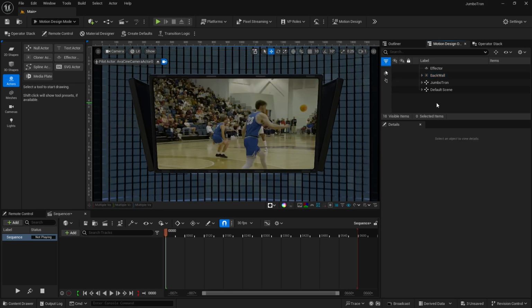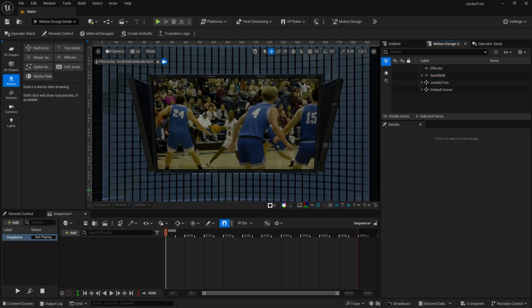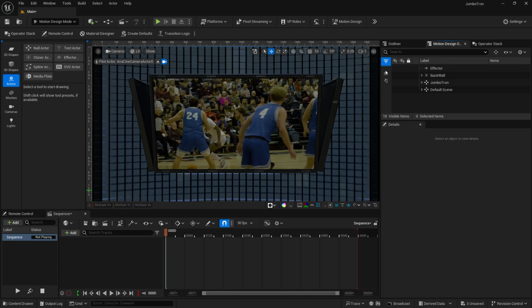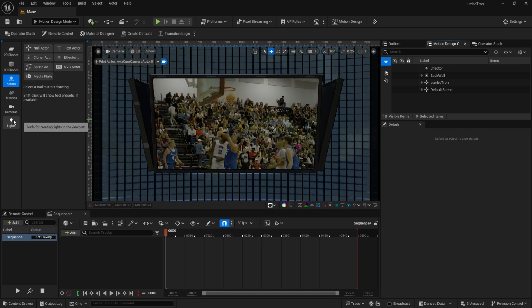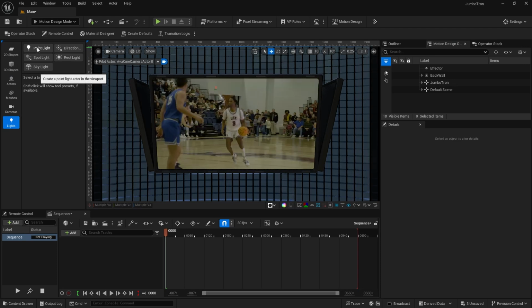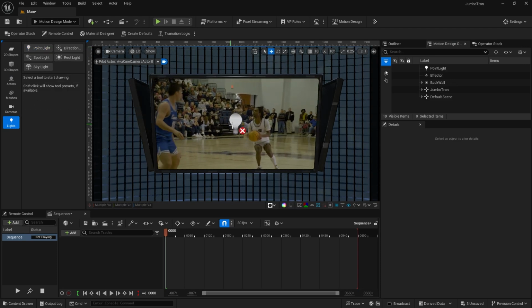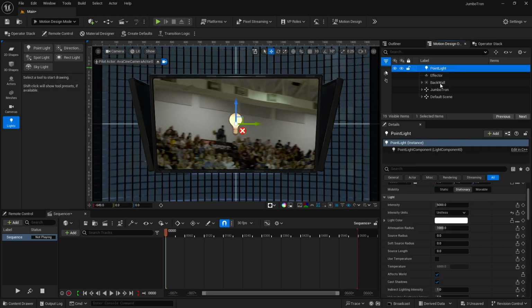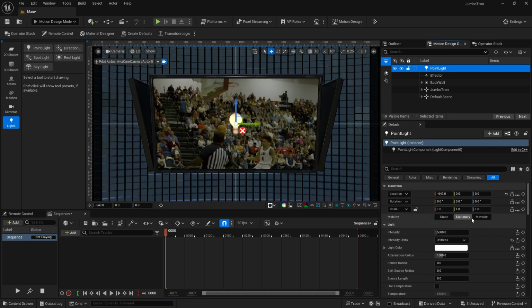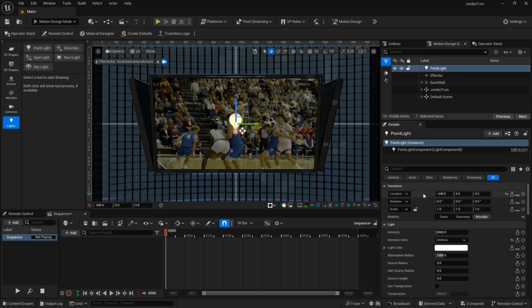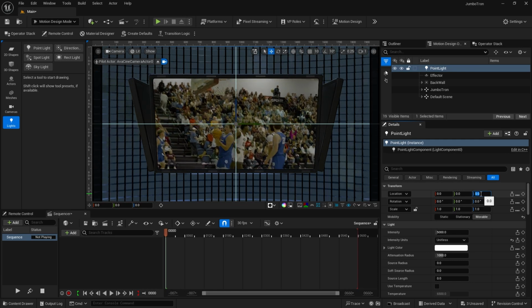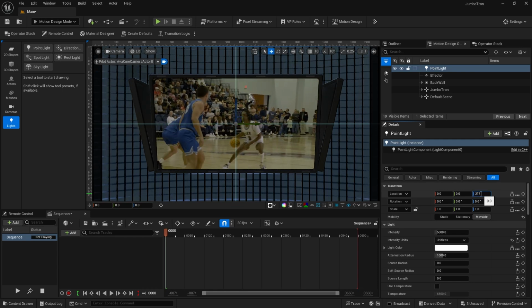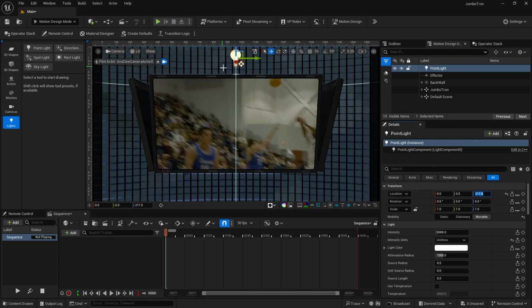We're going to start adding our lighting in. To light this scene, I'm using only 5-point lights, and we'll move them around. So we'll start off. Let's go over here to our tools, and we'll drop down to lights. And I'm just going to double click on that point light, and we'll make some adjustments to this first one. Select it, and let's change this to movable. And I'm going to reset that location, and then on the Z axis, I'm going to set that to 217. So we're bringing that up.